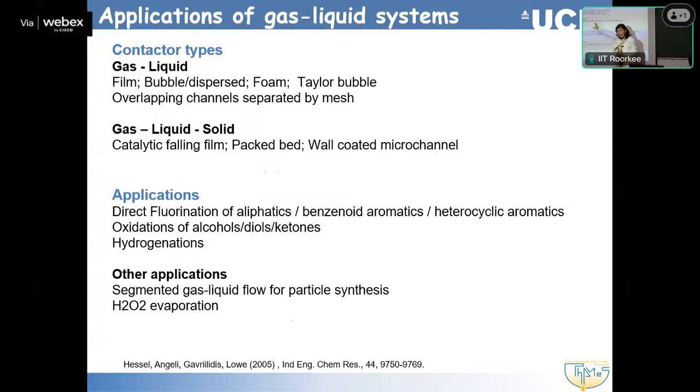If we have solids like catalysts in the mixture, if they are important, we can have the same as the film ones, with the wall covered in catalyst. There are micro-packed beds. A lot of people have worked with those, because one good thing with packed beds is that you can use commercial catalysts that have been tested. Because once you start fabricating different types of catalysts, for example to cover a surface, then of course the catalyst properties might change, or the mechanism of the catalyzed reaction might be different. While with packed beds it's much easier, because something that has been tested can be applied directly.